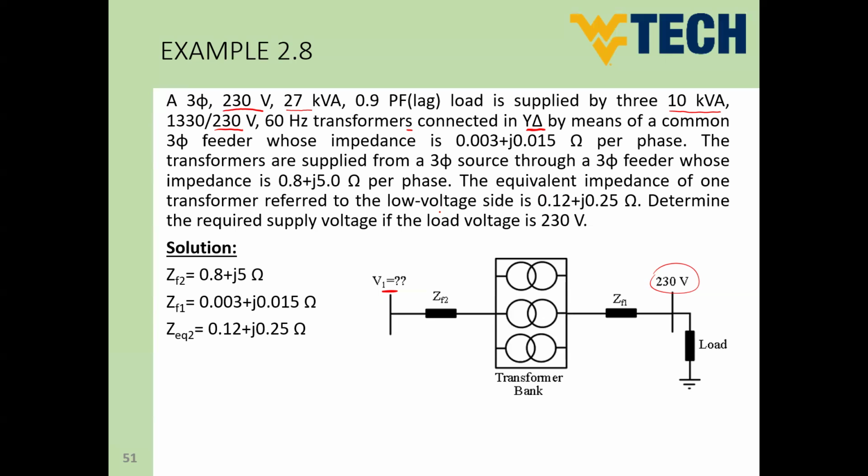But if you remember, guys, we mentioned before that this side of the transformer is considered medium volt, and this side is low volt. So most of the time, the primary and secondary connections of substation transformers or distribution transformers are not common. So the primary and secondary connections are different.